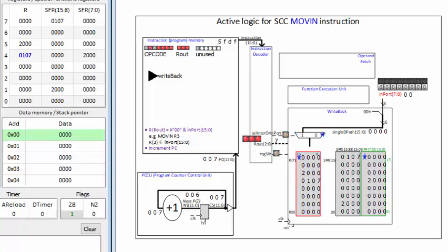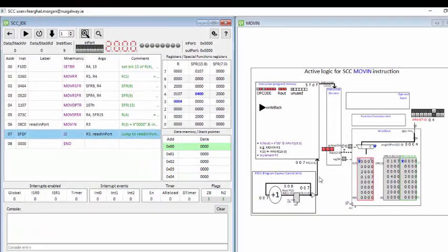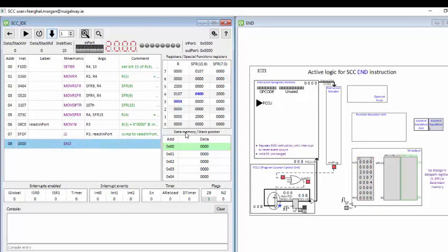And this will continue to the next instruction. This is a jump of 0. So if register 3 is 0, it steps back 1 instruction. In this case, I don't have a JZ jump instruction tab, so it's not illustrating that. There's another video that demonstrates jumps. I'm going to step again, and as long as there's a 0 on R3, it will continue to loop around here. So I'm just going to put the value 4. Any non-zero value on here will change this. And now register 3 has the value 4, and the jump of 0 will pass on to the end now. End program is asserted as before, and the program counter remains unchanged on every active clock edge.